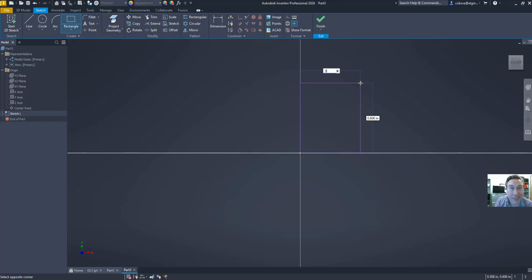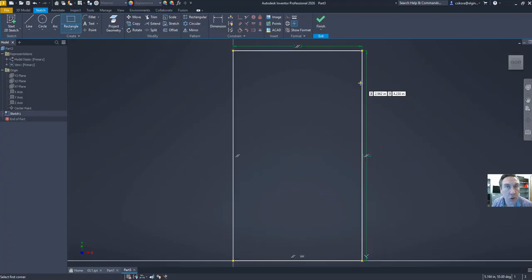So hit the Tab key in the upper left corner of your keyboard, Tab. Hit it once. And look at that. Now you could type in 5 and hit Enter. Now it seems to zoom out of the screen, or it's out of the screen as it enlarged. Now what you can do on your keyboard, find the Home button. Mine is up here on the keyboard. Some of you have it over here. But find Home, and you could click on Home at any time, and it's like a zoom to fit.